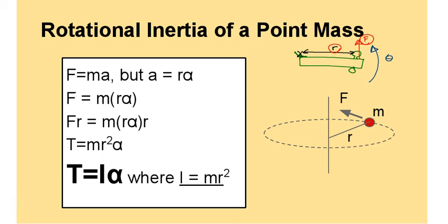This would be a very different problem if I pushed over here, or even if I pushed at the hinge. Try it sometime. When you go through a door, push right up near the hinge, the door won't hardly open. You have to push very hard to make it work. We call that concept torque. And again, torque is simply the force times the distance. The lever arm, the moment arm, it has different names, but it's the distance from our point of rotation. So we've got that torque right here.